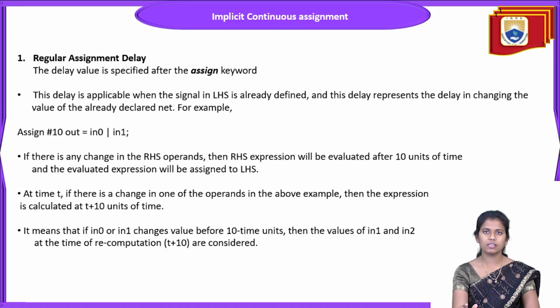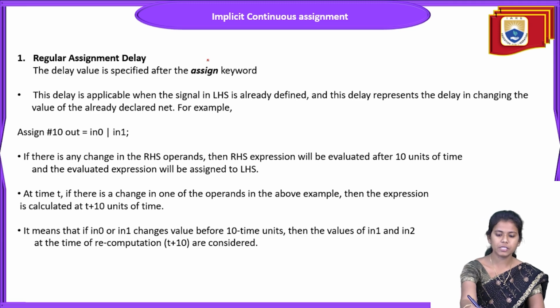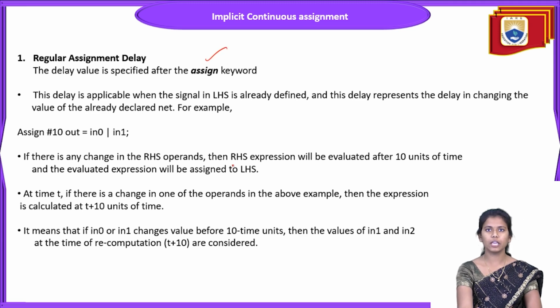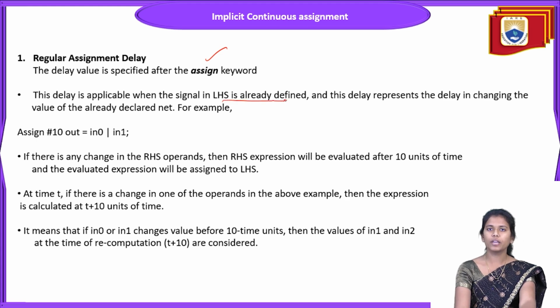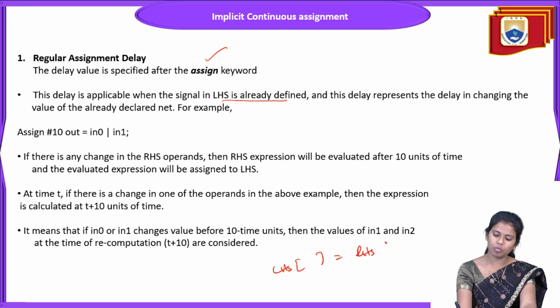What is this regular assignment delay? This delay we specify with the assign keyword, and the delay is applicable when the LHS is already defined. In our expression, the LHS is already defined with some delay and the RHS is some expression.